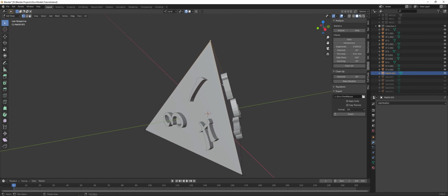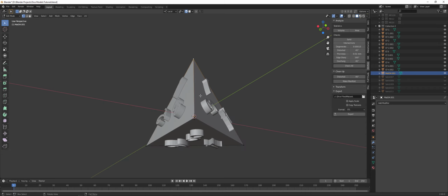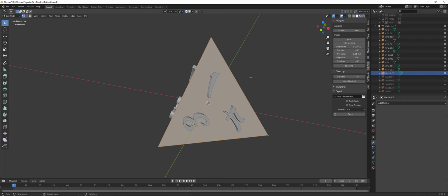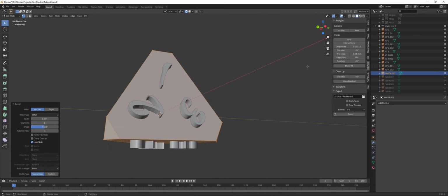and if you want your dice to have beveled corners, you're gonna grab your corners with the vertex mode in edit mode, and you're gonna do Control Shift B. That will allow you to do this. Now, with the scroll wheel, you can change the number of vertices you want in your bevel if you want rounded edges, rounded corners. I personally like the flat bevels for the D4. With 1 or 2, with the numbers, you can actually type in exact amounts of bevel, right?